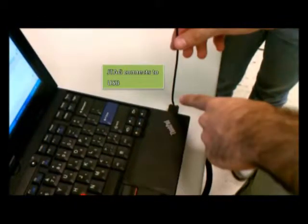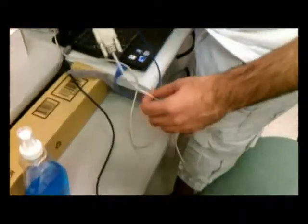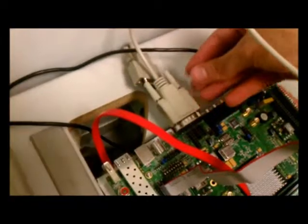Next, we have a serial cable. This cable is used to send information from the FPGA board to our laptop. The cable is connected to a USB serial adapter and connects to the serial port on the FPGA board. To make use of the serial cable, we have to implement a UART peripheral in our FPGA board. To implement these peripherals, we are making use of specific software called Xilinx Platform Studio.